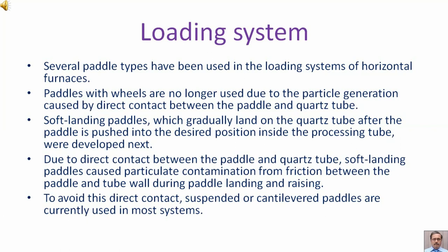Soft landing paddles, which gradually land on the quartz tube after the paddle is pushed into the desired position inside the processing tube, were developed next. Due to direct contact between the paddle and quartz tube, soft landing paddles caused particulate contamination from friction between the paddle and tube wall during paddle landing and raising.